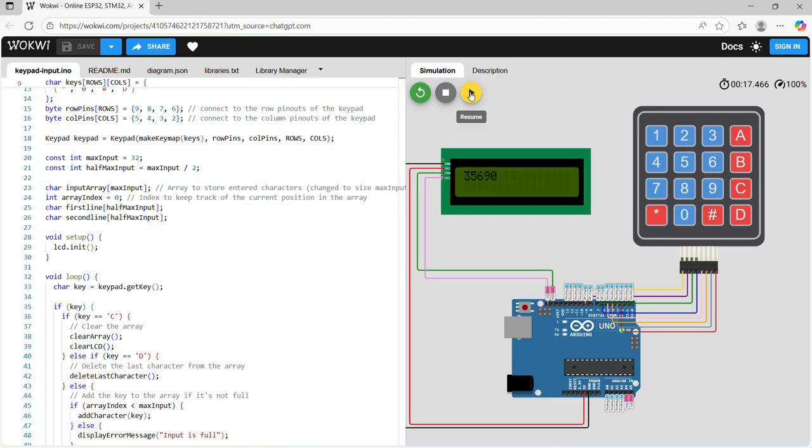So overall, I have explained all the things related to it. To conclude, this project successfully demonstrated interfacing a 4x4 matrix keypad and a 16x2 I2C LCD with the microcontroller. I have learned about GPIO pin configuration, matrix keypad scanning, I2C communication using Arduino and testing in Arduino simulation. The same concept can be applied to password and login systems, calculators, and menu-driven embedded systems.